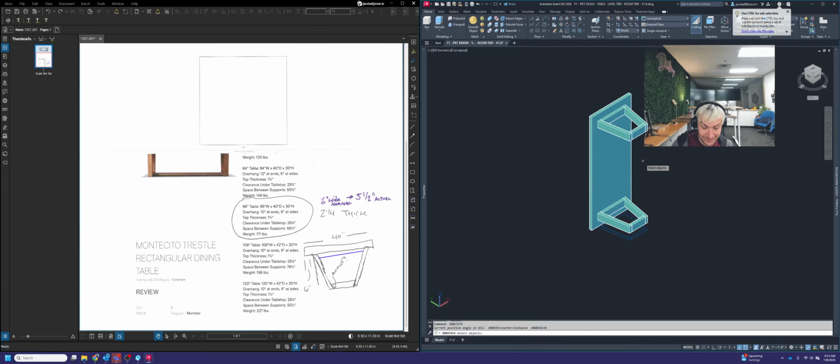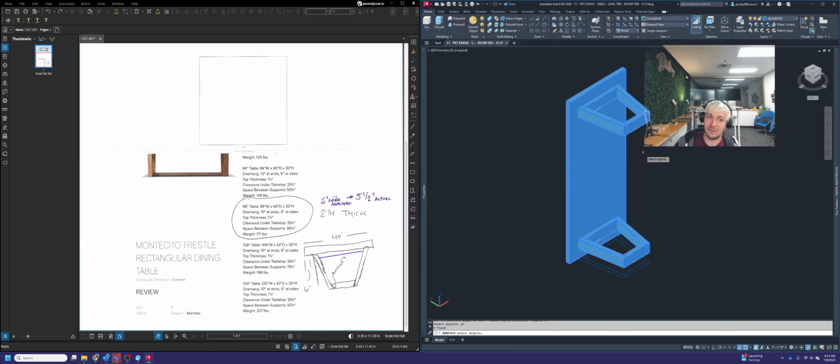And fun fact too, if you already had something selected and you want to reselect those parts again, once you start a command, type in PR and hit enter. It will automatically reselect the last object selected. So if you mess up something by mistake, you can use that to quickly get back to where you were.